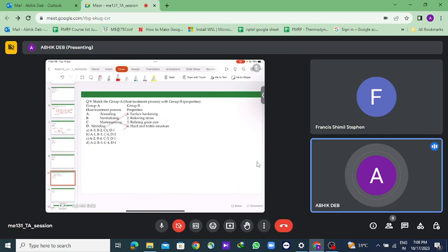That is, the decrease in ductility or toughness will be less, but there will be a quite significant increase in the hardness. That is related to normalizing, that is refining the grain size. Okay, so the correct option will be A, B with 3, C with 4, and D with 1.